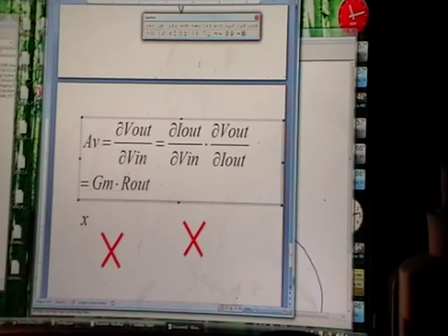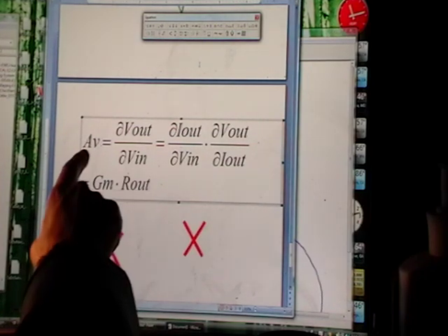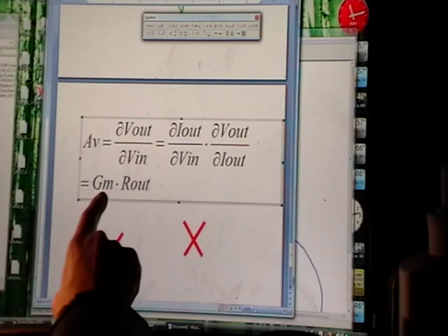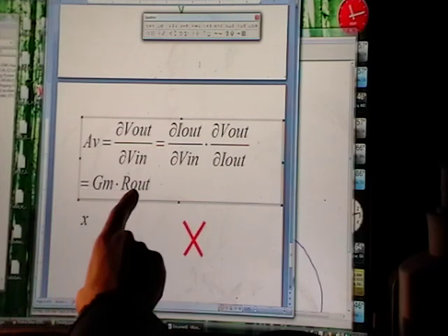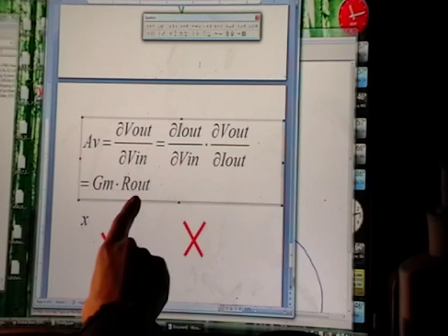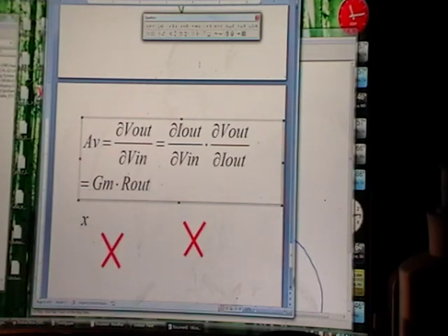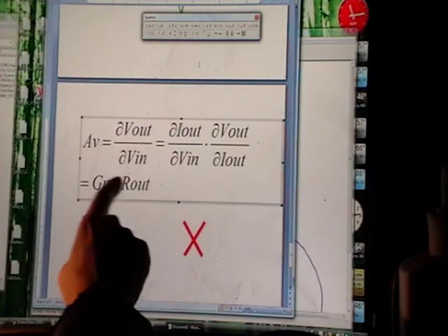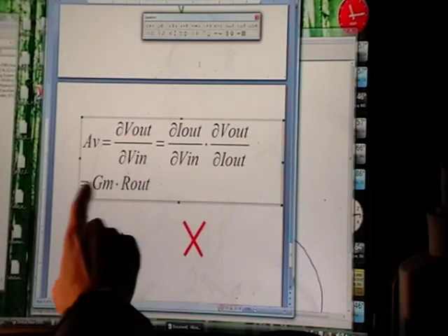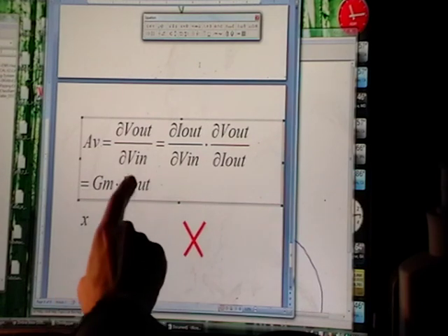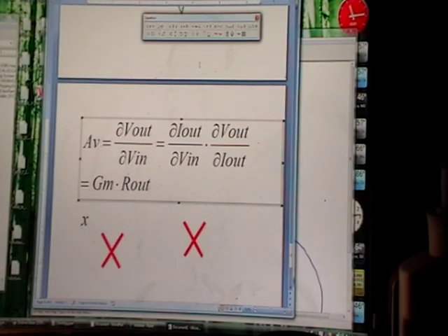So in class we calculated GM, and assuming Dr. Pradnov's class has already looked at GM, but right here what this says is the gain is GM times your R out. If you make R out bigger, that gives you more gain in general. And there is a trade-off.